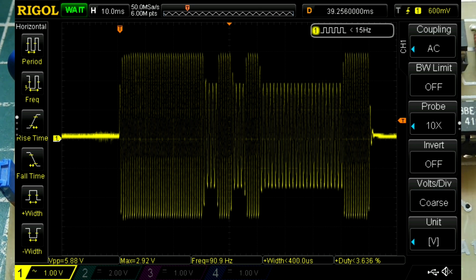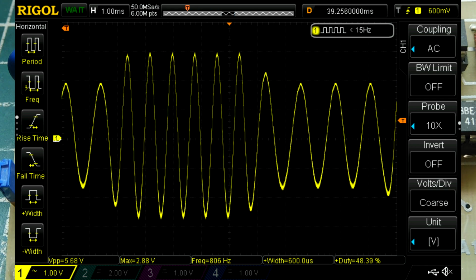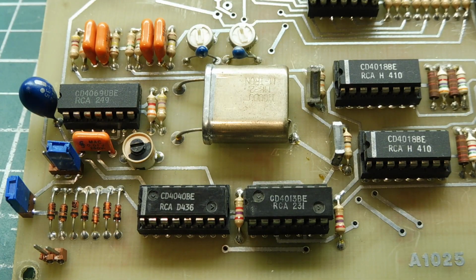And I'll go back to the normal speed. And if you look at the scope, you can see the burst of data, and if we zoom in, we can see that the transition from the mark to space frequency happens at the 0 crossing. That's very important. Okay, so we can modulate our FSK encoder with a UART signal, and here's the UART protocol.